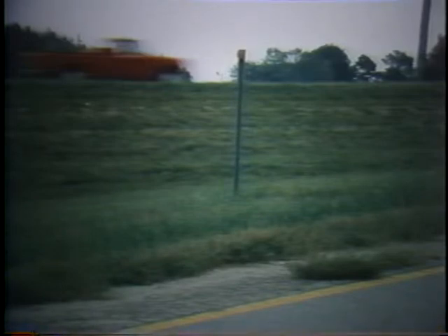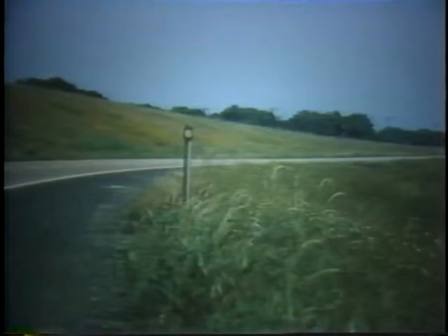The MUTCD also states that post-mounted delineators shall be placed on the right side of expressways and at least on one side of ramps. The MUTCD also says that delineator posts should be located 2 to 6 feet outside the edge of the shoulder or curb face and should be about 4 feet above the road. When a hazard exists on the paved roadway surface, the delineator should guide the motorist safely by the hazard. So that the reflective element won't be a flying hazard, it should be firmly attached to the post. A washer should be used so that the reflective element will remain on the post when it is struck.